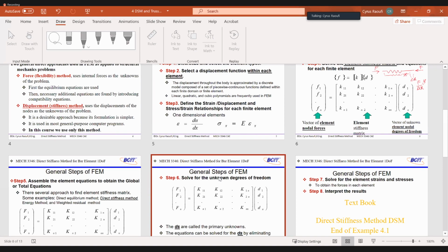Then you need to at least verify your result. And what was the verification? Verification was, if you go back to chapter 2 in terms of the definition and a couple of my slides, verification is the process in which you verify your FEA model in SolidWorks simulation by some other mathematical model.